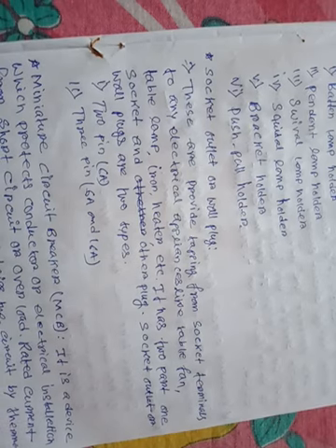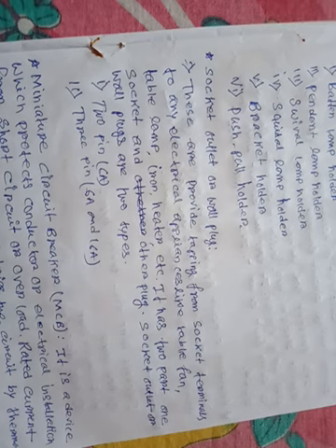Next, the miniature circuit breaker, whose short form is MCB. It is a device used for protection purpose. It protects the conductors and the electrical installation from short circuit and overload. The MCB is a self-operated type of device, used for protection from short circuit and overload.